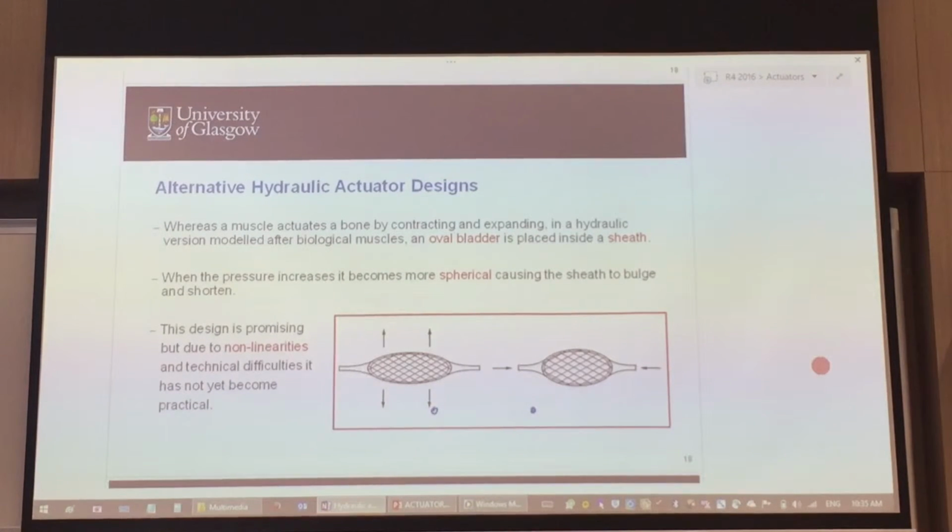You can see that the way that this arm moves is actually not very precise. And not only that it's not precise, it's actually hard to use a proportional valve to actuate it because of the integrator. So that integrator is going to introduce non-linearities in this movement. So it's not whatever amounts that you energize it correspond to a linear response. It's non-linear. That's why you can see that its movement is not very smooth.